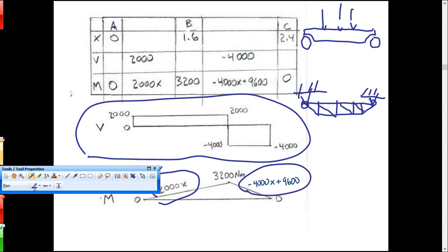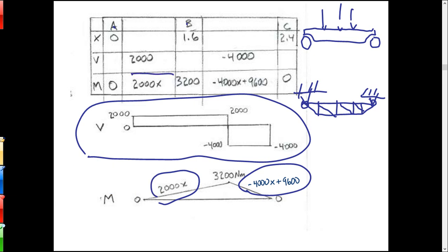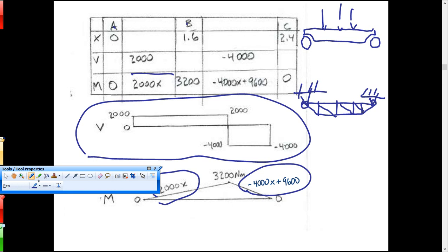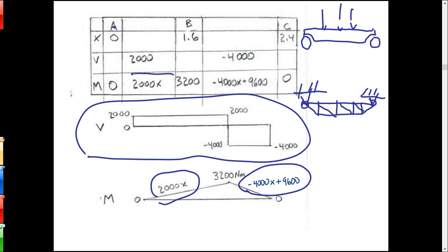If I were doing this, like I set them up for your homework, I've just got a piece of graph paper and everything just lined right up. So what I've got there is a loading diagram, like so. And I've got what, 2,000, 6,000, and 4,000, right? So I got 6,000 right there, and I got 2,000 right here, and then I got 4,000 right there.